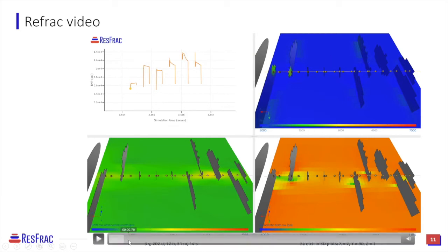It's an isolation difference. If we look at when the refrac is starting, in the pressure plot in the upper right, we can see that the existing fractures are being repressurized and no new fracture forms in this first stage, even though there are 3 perforation locations in which it could.